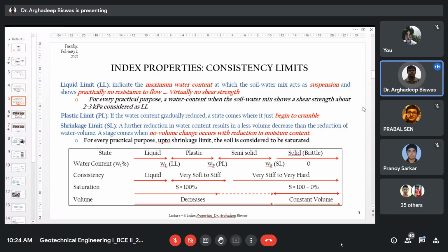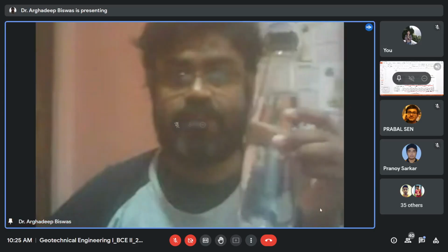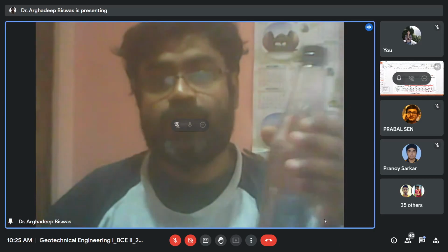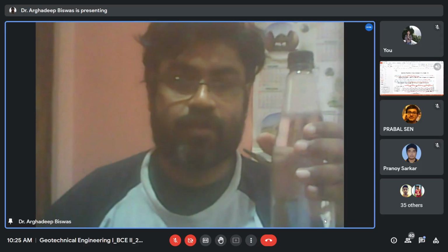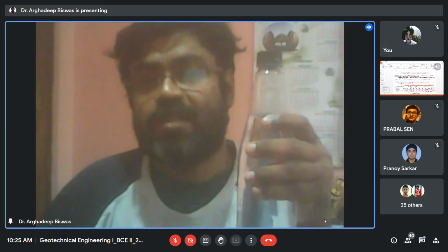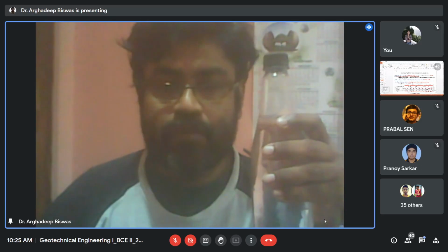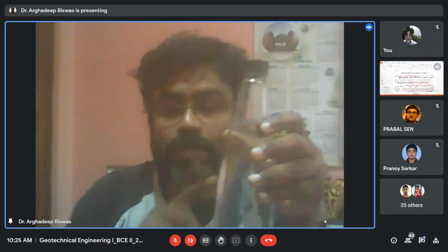Now plastic limit. I am keeping my video on, that will be easier for you. Now this body is a mix which has achieved 2 to 3 kilopascal of shear strength. What the plastic limit is mentioning is, if the water content is gradually reduced, a state comes when it just begins to crumble. Now what you can do, you can extract the water here.